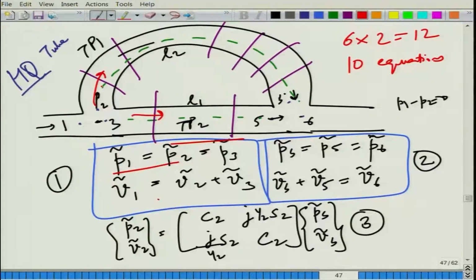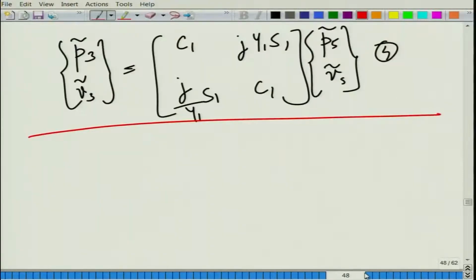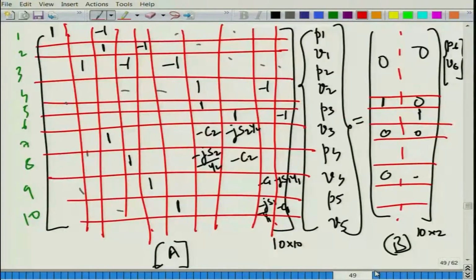We set up the different equations and figured out that simple cascading of transfer matrices can't really be used. One has to write down the different equations that characterize each element and the junction laws itself, and then assemble all the things into one big matrix like the one that we are seeing here, represented in terms of the variables pertaining to the downstream ones. So, this matrix needs to be inverted and then multiplied.